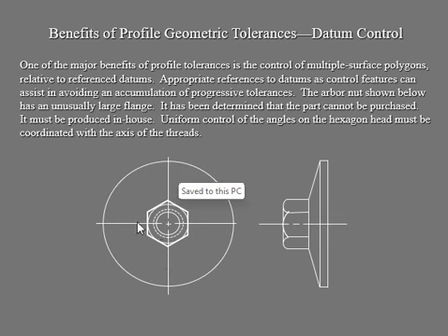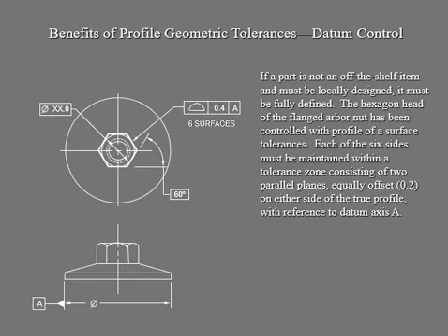So we have our axis, thread right there, and everything has got to perfectly coordinate to each other with these nut surfaces. So here we are, and this is the control frame for this profile right there. Of course, the angle between this profile and that is going to be 60 degrees. Your datum is right there, which is your datum A, the primary. So the touch point, three points in contact. And then, of course, your diameter, you have a value for that diameter.